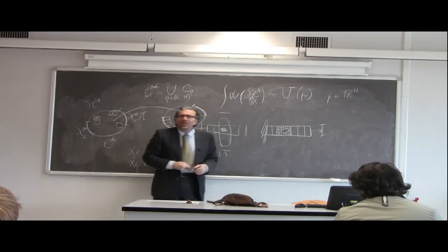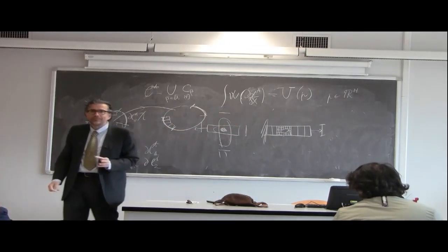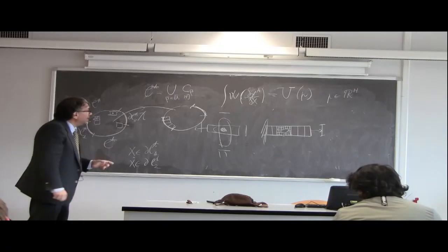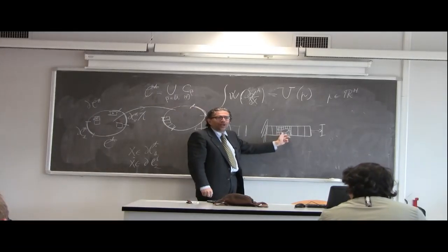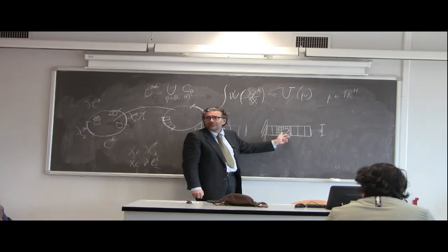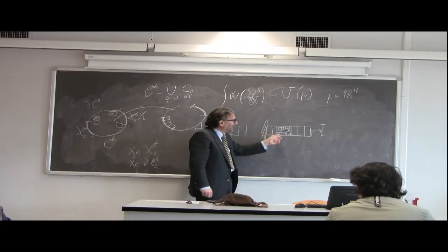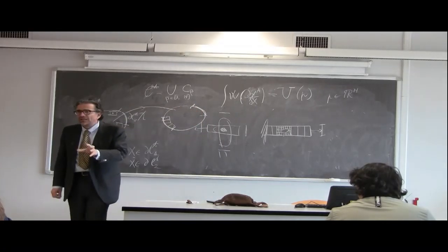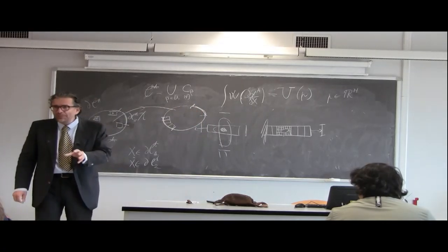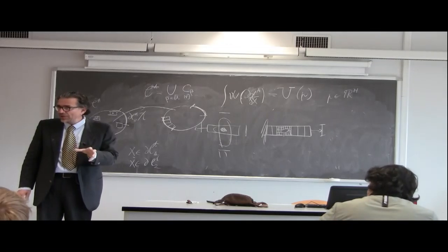So we built a mesh with varying size. And maybe here it is better if we use a polynomial of higher order in order to represent better the deformation state of your body there where we expect bigger deformations.